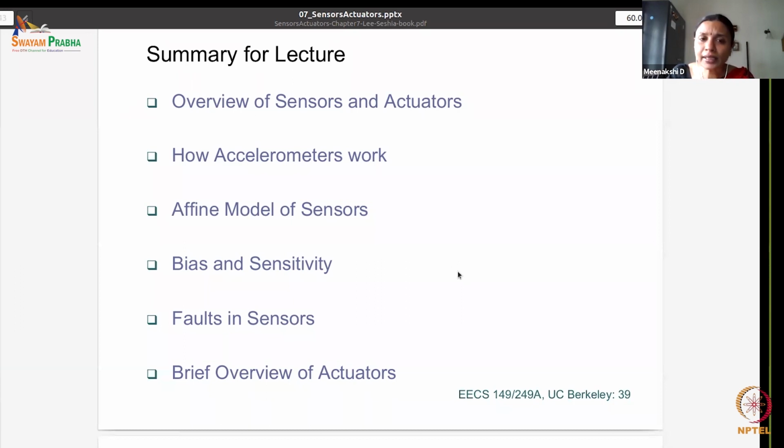So, in terms of practical issues, what are the issues? Sensors measure analog data, which has to be converted to digital data for our processing. Sensors could be wired or wireless, and they come with their own challenges. They could be connected through serial ports or parallel ports. As I told you, they could be sampled at regular intervals or they could be sporadic, triggered by the presence of an event. The rate at which you sample them matters. How secure are they? Who has access to that kind of data? That also matters. What are the physical connections between them? What is the electricity requirement between them?